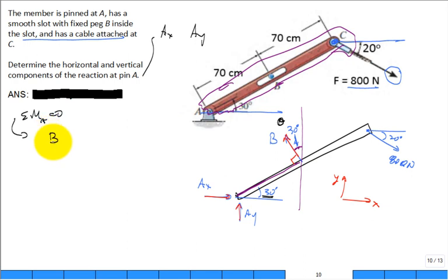So, does B induce a moment about point A? Yeah. What is its moment arm distance? 70.7 meter or 70 centimeters, isn't it? Yeah. This one's easy because that's your moment arm distance coming out. All right. And then that's going to make it want to rotate in the, I'm going to do this one. This will be positive. The counterclockwise will be positive for this problem. All right. So that'll be positive.